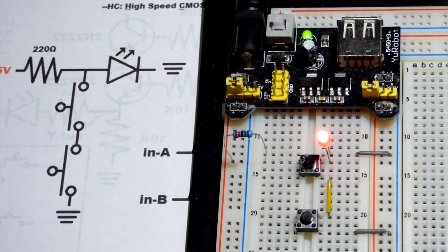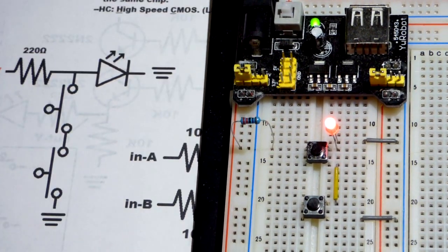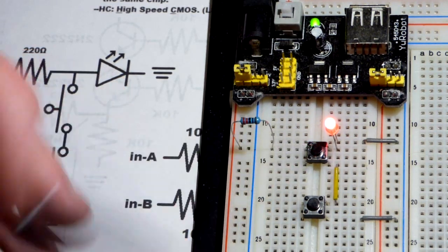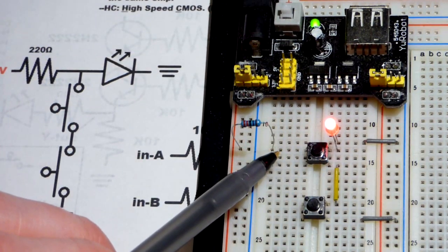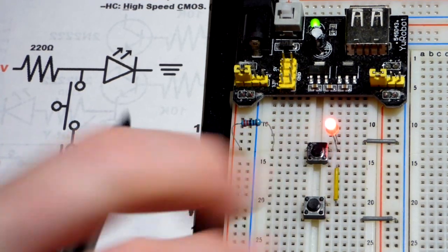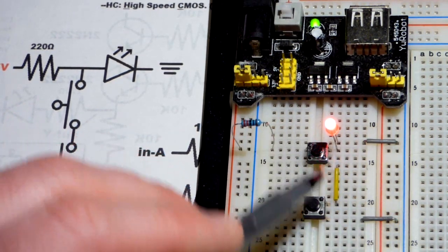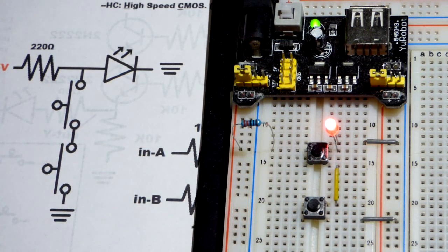So the basic principle is pretty simple for this type of NAND gate, and we are diverting the current. So when we press both switches, whatever energy gets through the resistor to push the current gets to that top pin. When we press both of the switches, then it connects directly down this path to ground, which is a lot easier to go to than through the load, which is just an LED here. And that's the basic principle of a simple NAND gate circuit.